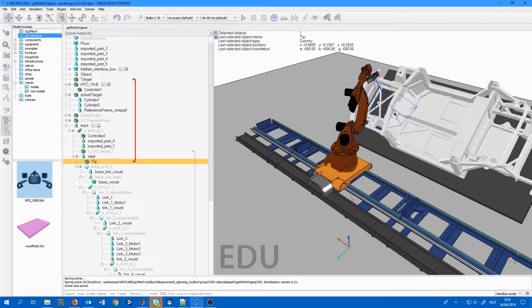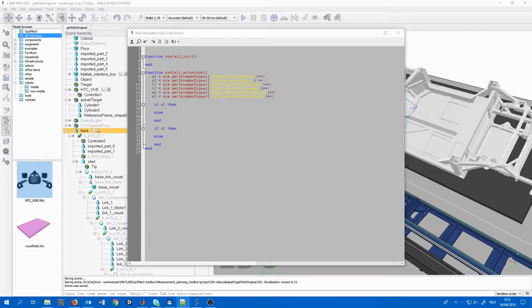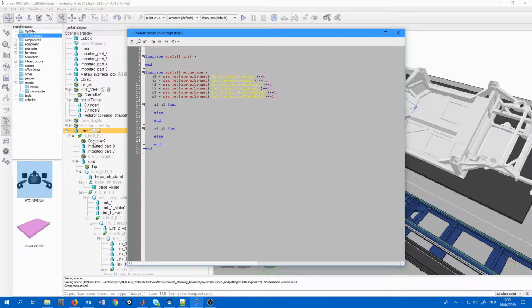Now the inverse kinematics is fixed, and we have basically separated the card inverse kinematics from the robot's inverse kinematics. When we push the grip button, the target will follow the movements of the controller. So what we actually want to do is make the tip of the target object a child of the controller. If the controller moves, then the target object will follow. That's exactly what we want.